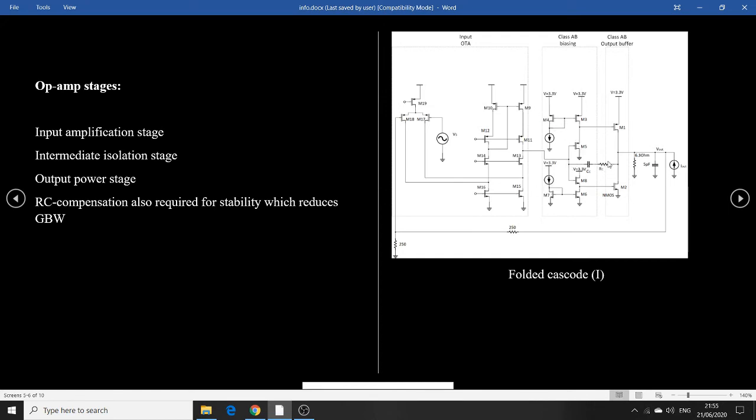And this is for the compensation. These RC components here, and these C and L represent the power amplifier, because the power amplifier is connected to this op-amp in the linear amplifier, which is a part of the split stage ET system. So this is just modeling the power amplifier part, and this is the feedback resistance. You can ignore these for the moment, but this is the main folded cascade architecture.